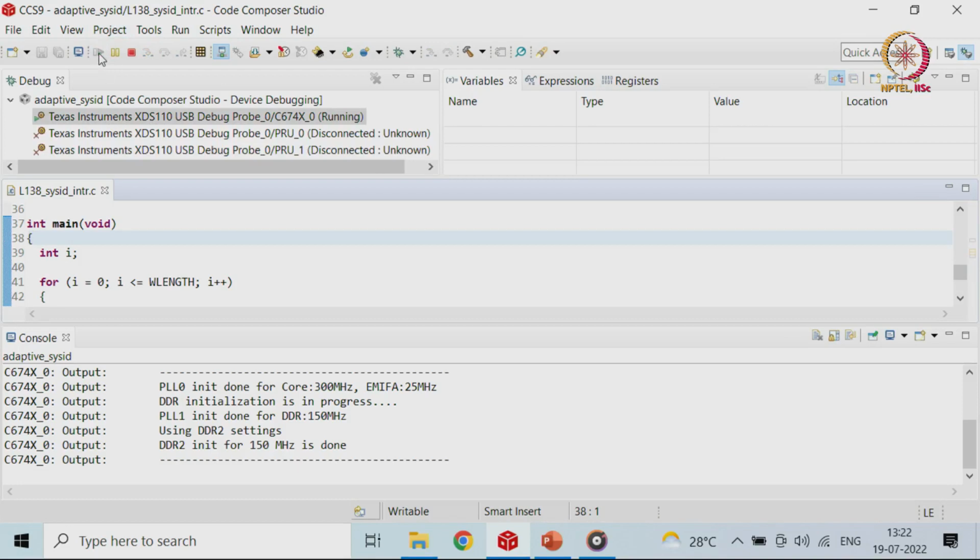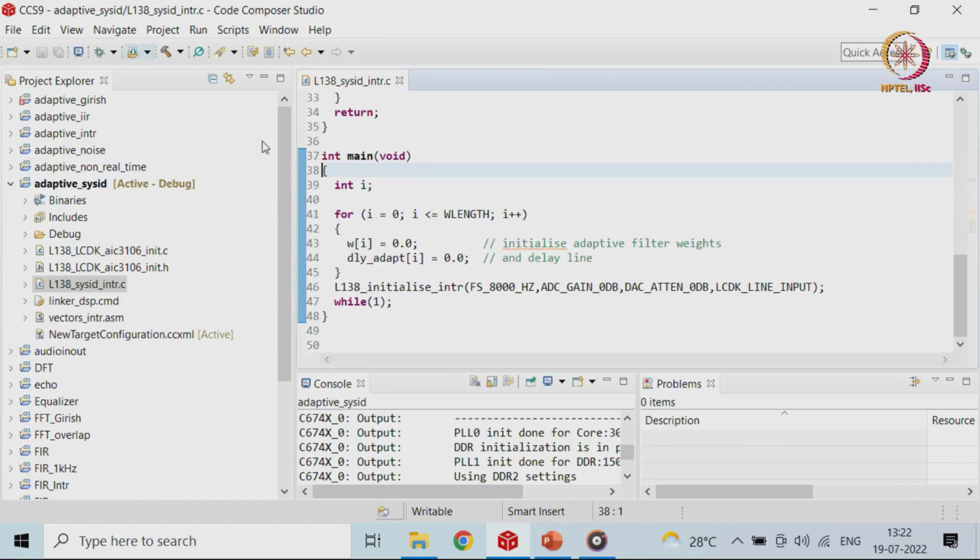As you can see, there is a little error in whatever the FIR filter is getting adapted to, that is, the filter coefficients trying to remove this noise, and then I should be getting a clean sine wave, but still there is an error. So, this order may not be sufficient for it. You may have to go to a higher order to remove the noise. It is a little bit reduced, but it is still getting overlapped. So, you have to fine tune and then work on it.